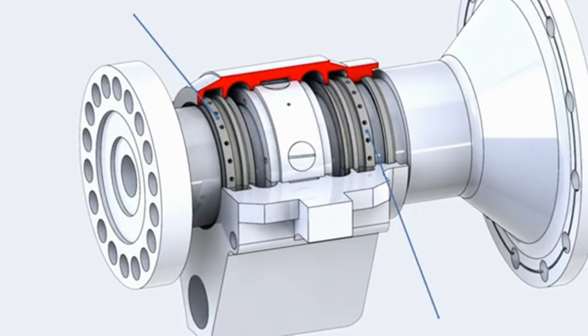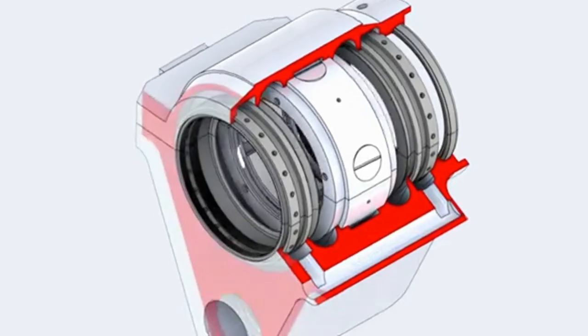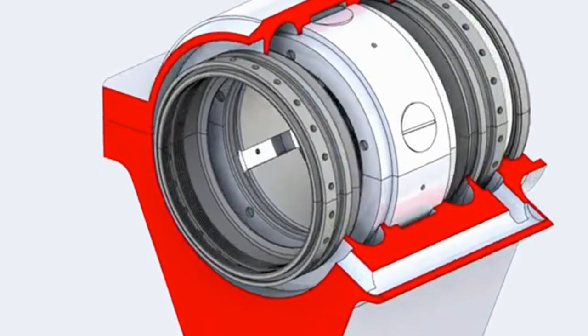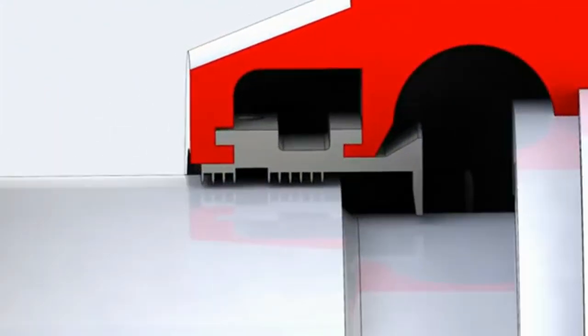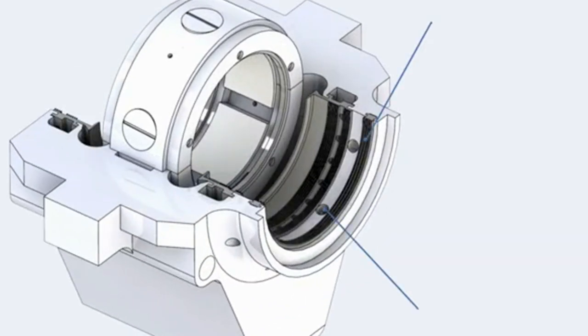The sealing air flows from the cooling and sealing system through the axial tube machined at the left side of the housing and is admitted to the labyrinth seals through 2 ports to annular spaces surrounding the seals. Between the 2 rows of seal teeth, similar to other bearings, sealing air is admitted through multiple radial holes to stop oil leakage. Some of this air returns with the lube oil, and some escapes out of the housing. A forward air deflector seal is installed at the forward side of the housing to prevent crossflow, and vent holes are machined on the housing.